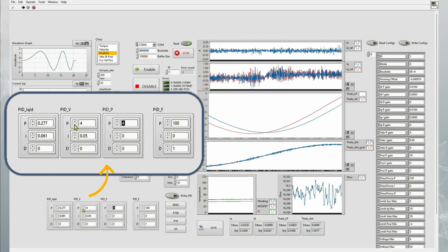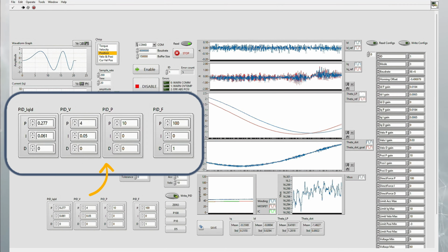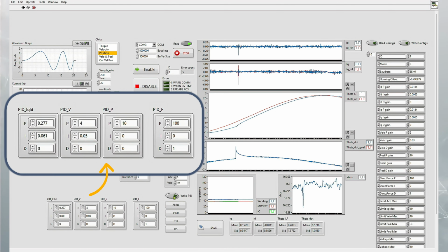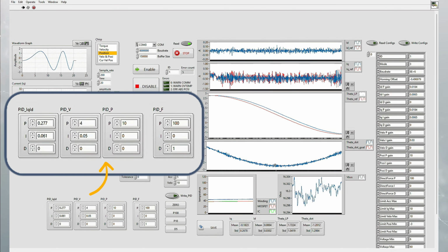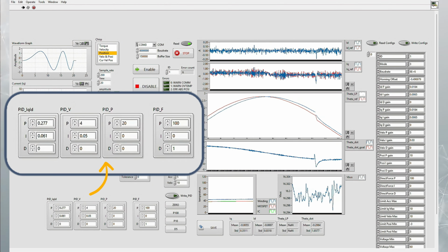Step 2. Boosting rise time and stiffness. Gradually scale up your position P gain. As it increases, you will feel the static holding stiffness of the joint multiply, and the tracking response toward the target coordinate will significantly accelerate.